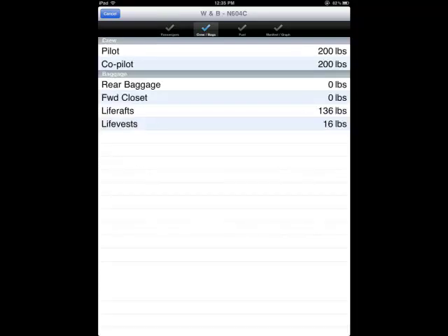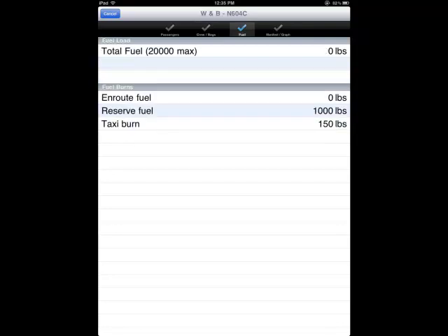As stated before, the crew weights are not included in the BEW. Instead, they are displayed here for easy alteration. Baggage compartments are listed below the crew. When satisfied with the entries, press the checkmark tab named Fuel. The Fuel tab contains separately identified fuel tanks and their maximum weight limit. Enter the amount of fuel on board.